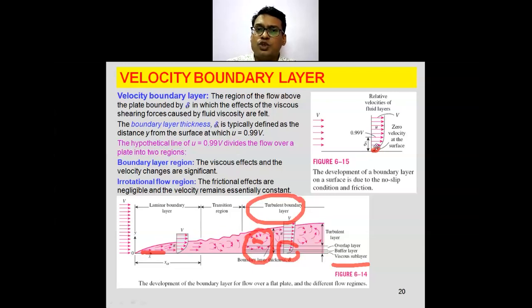So if the velocity vector is small, its magnitude, its numerical value, is less. And that means in this viscous sublayer the gradient is high. Variation in the velocity is high because of this viscous sublayer. Then slightly in the buffer region, that variation decreases. You can see this curvature, this section of the curvature. That is your buffer layer, where you can note that the velocity gradient has decreased. In the initial part, the velocity gradient is more. Then in the buffer layer, the velocity gradient is less, and after that the velocity gradient is more or less the same.